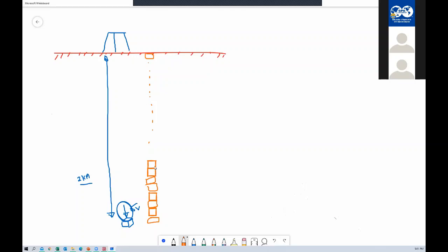When one rock is placed above another rock, it will apply some gravitational force on the rock on which it is lying. When two rocks are placed on top of another rock, together they apply a certain force on that rock piece, correct? So this is the concept behind overburden stress.